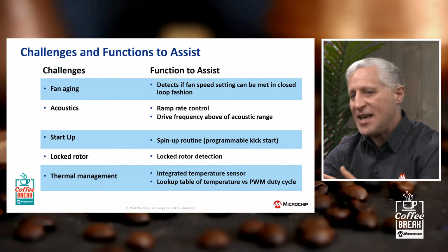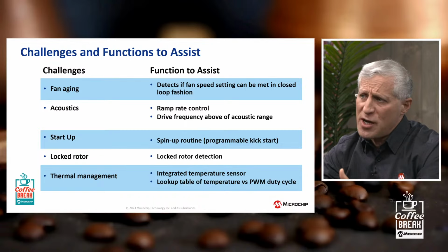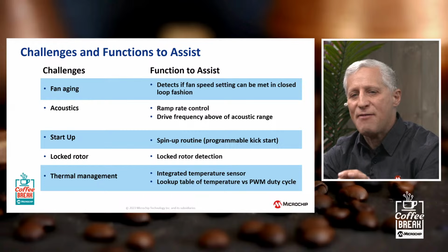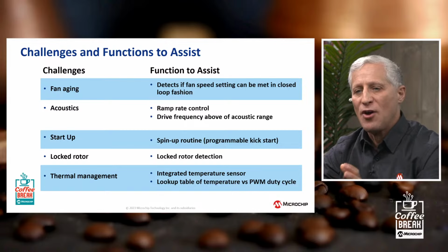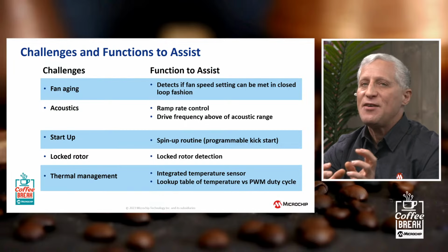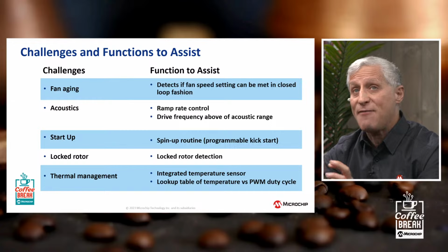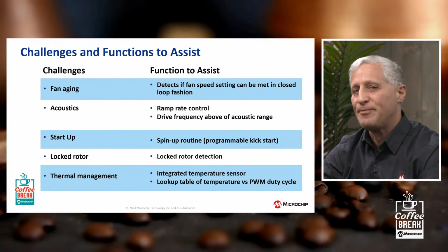But lastly, it's nice for everybody to know that we actually have some fan controller ICs that integrate the temperature sensor and help us set both temperature and fan speed in conjunction and have a closed loop algorithm. Okay, so you can monitor the actual temperature that you're getting and adjust the fan speed accordingly to accommodate for being over or under the target. Exactly.